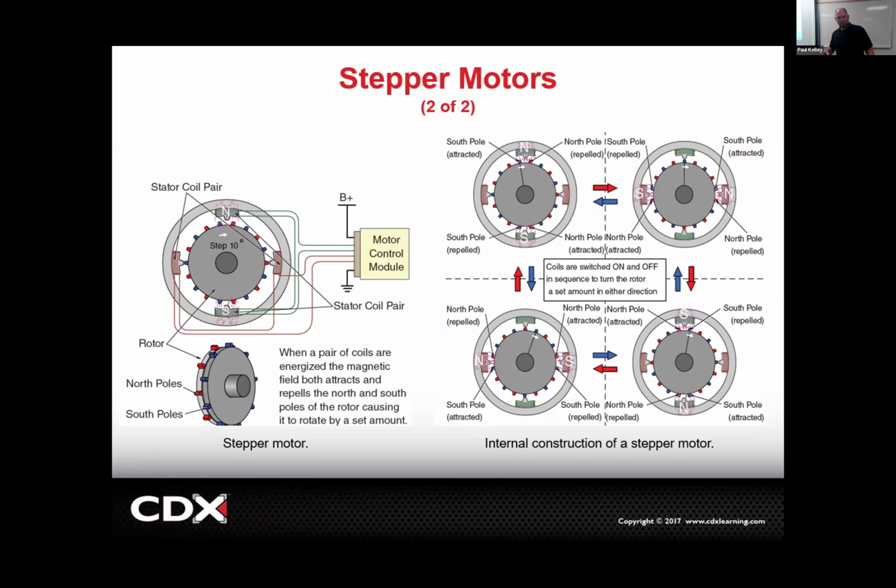But how? Well, that little needle that moves, we're actually going to connect that to the center of this stepper motor. And then we're going to use the control module, and we're going to say, hey, it was on E, so that would mean line up right here. But now that you filled it up, we're going to have it run the motor 1, 2, 3, 4, 5, 6, 7, 8, 9, 10 steps, and that would read full. So your actual gauges move the needles on a stepper motor. The reason that I'd say that's really good to know, let's say you get a customer car in or your own car, and the gas gauge doesn't read right.